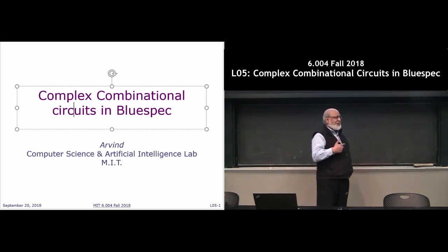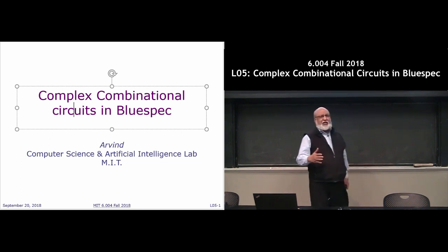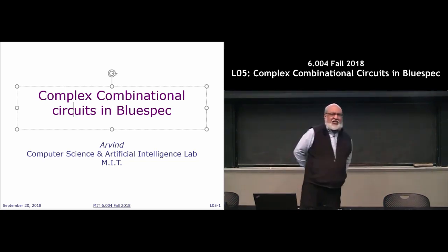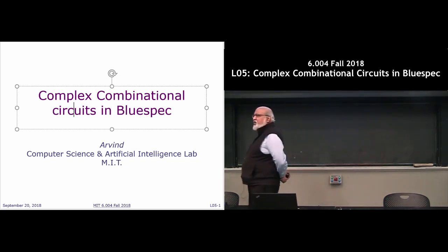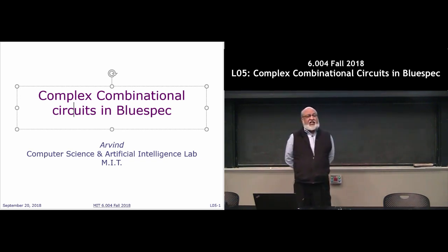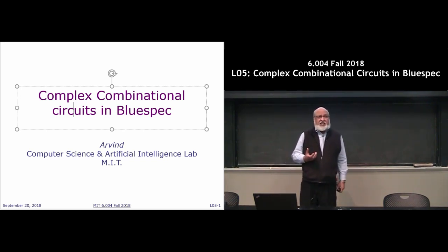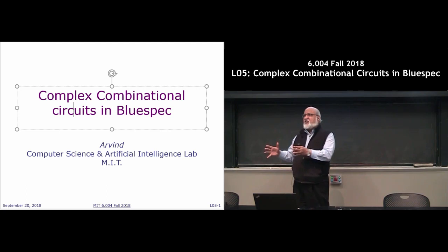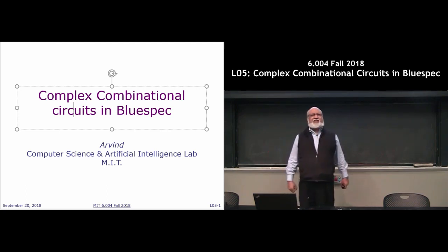This is just software-hardware interaction, but there is no operation. There were 2 wires coming out. I refer to them as CS0 in my program, but one of them, when I select it, is connected to the next full adder, and the other one goes out as the sum bit. Good. Each instance of function FA is replaced by its body. So now I can go and say, what do you mean by FA? It's a function call, right? One and only one meaning: go and take the circuit corresponding to the full adder and put it in here.